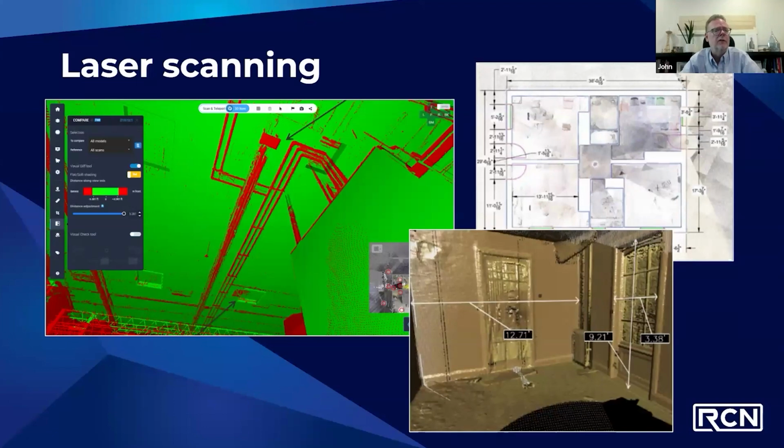There are best practices, obviously, around making sure that you've scanned correctly, making sure that you have control set up and geospatial coordinates and whatnot, so that everything lines up the right way. But it's really powerful, and there are tools out there now that allow you to have that common data environment for laser scanning, so you can share it with the rest of the stakeholders.